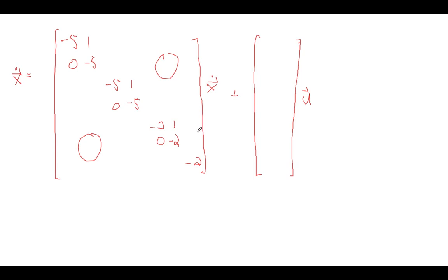Now, if you think about the structure of this matrix, and you think about what we learned on the previous slide, what we come to realize is we need to be able to control the bottom row of each Jordan block. So I'm going to draw a line over here. And there is a row associated with this B matrix right here. And it's important that that row isn't 0. Now, the question, if there's multiple columns, is what is the equivalent of 0 in this case? And we'll talk about that in just a second.